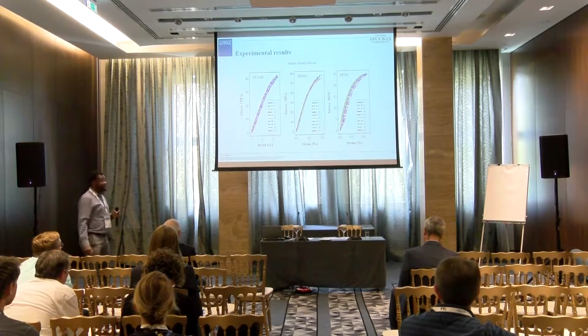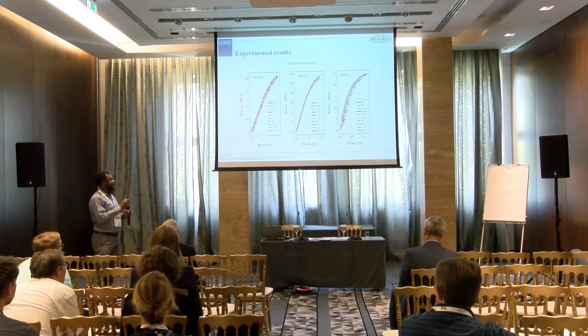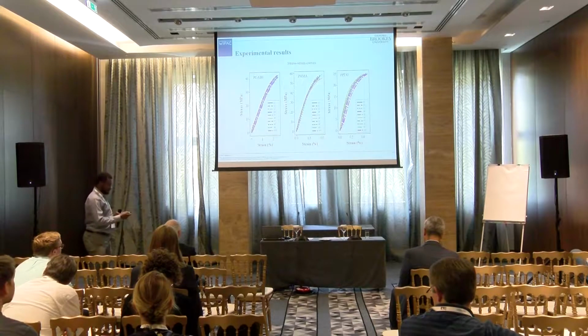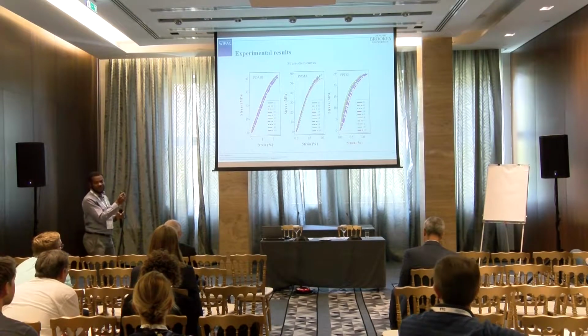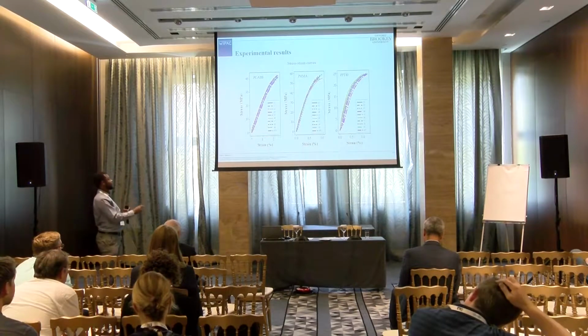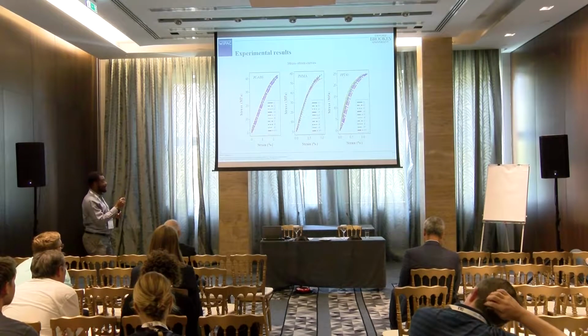And here are our experimental results. This is our stress-strain result for PC/ABS, PMMA, and PP-T40. For PP-T40, we can see that it has a huge intersample variation, and the nonlinearity is quite huge compared to the other 2 materials, PC/ABS and PMMA.